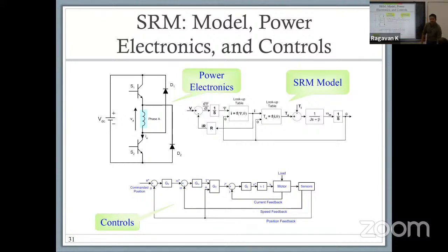So shoot-through failure basically is the possibility where, because normally if you have a full bridge with multiple switches, you might turn on one phase and it runs through the phase winding to another. But there are two switches kept next to each other, and the phase winding is connected from the midpoint. Normally the way you operate the system is that you turn on the top switch and the bottom switch for another phase leg.